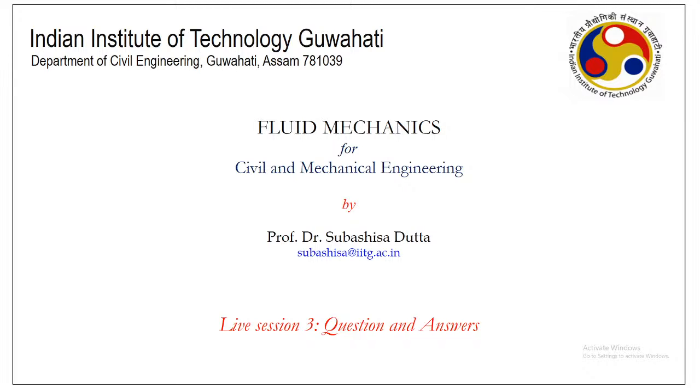In a very basic way, we have been discussing the linear momentum equations and Bernoulli's equations. If you look at the derivations of Bernoulli's equations, highlighting the assumptions part, you try to understand more details to solve any real life problems. That is my objective in developing this course: to understand the concepts of fluid mechanics through the Reynolds transport theorem, mass conservation and momentum conservation. Bernoulli's equation is nothing but the linear momentum equation applied to a stream tube, for steady, incompressible, frictionless flow, where viscosity is not dominant. Those are the regions where we can apply Bernoulli's equations.